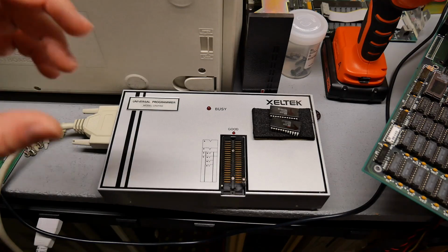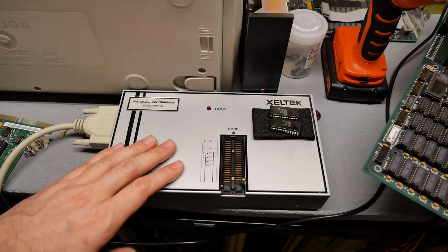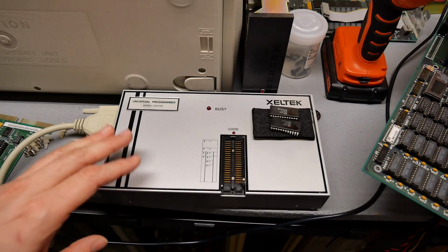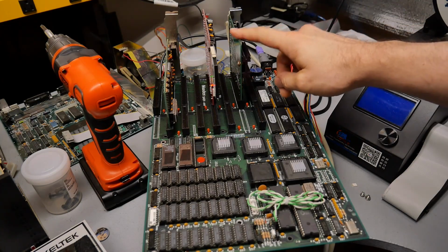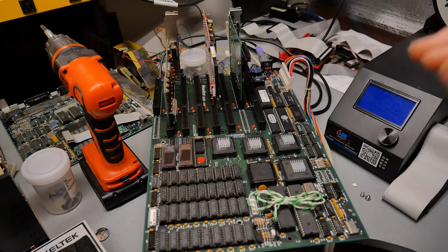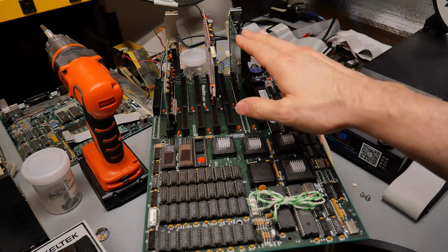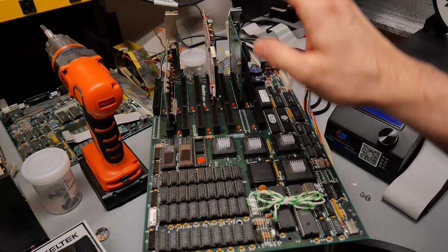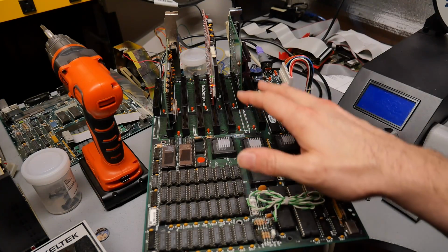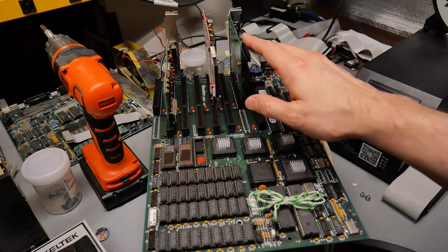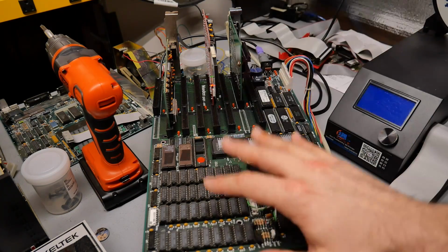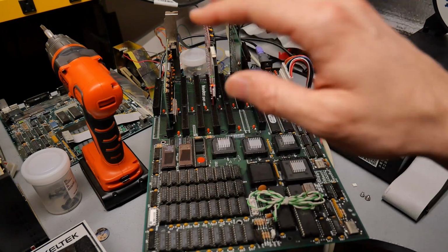This is a PC interface type of programmer, but it's old, and so it supports older chip types that the TL866 USB programmer doesn't support. It connects through an ISA card on a 286 or an XT, and it has to be a slow machine. It does work on newer machines like a 386 or 486, but the problem is if the clock speed is over 10 megahertz, which it states in the manual, you get all sorts of communication errors and problems. So I have this 286 motherboard here running at, I think, 6 megahertz or 8 megahertz, and it is absolutely working fine on this.